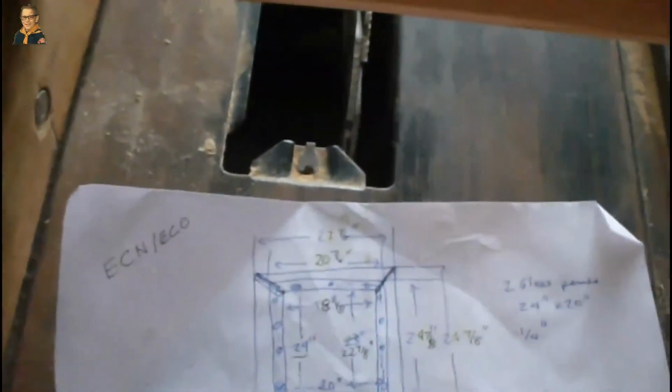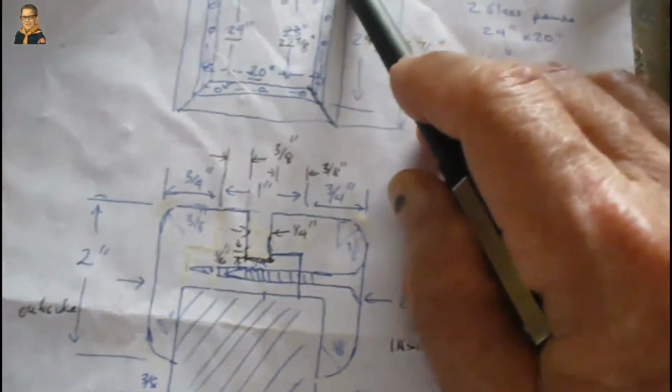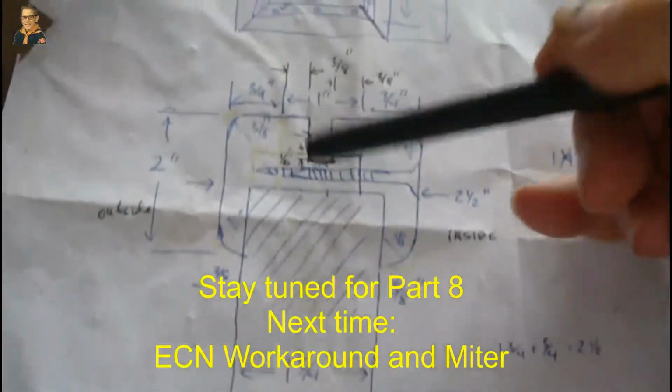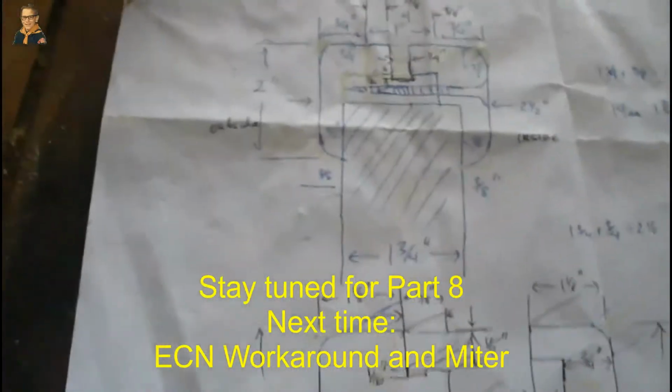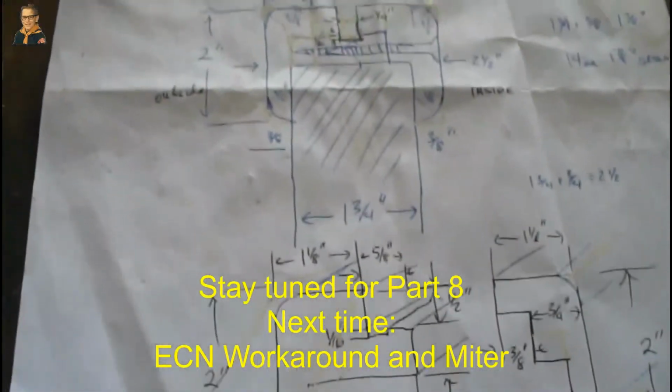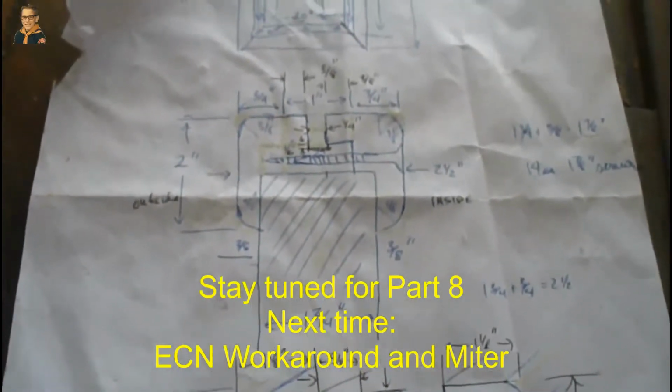So now, I think the first thing I'm going to do is dado these guys and put in that 1/16 gutter. The next one is 1, 2, 3, 4 cuts. 1, 2, 3, 4 more cuts. So 8 cuts, and then 9, 10, 11, 12. So I've got 12 cuts, and then we're going to start gluing this stuff together. So let me get that prepped up. You've already seen a dado run, so the next time we're going to be trying to glue.